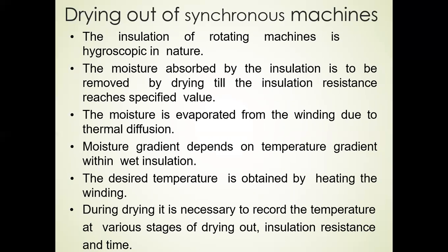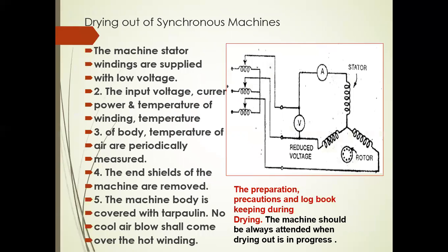So here the insulation of the rotating machine is hygroscopic in nature. So always the moisture absorbed by the insulation is to be dried out till the insulation resistance reaches its specified value. So here, this is one experiment for drying out the moisture existing in the machine.